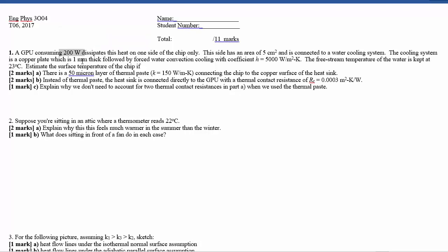So if we've got really efficient heat transfer, from low resistances and really effective convection, then we would need a low temperature gradient in order to drive that. So low resistance means you don't need as much of a temperature difference to get the same heat flow.